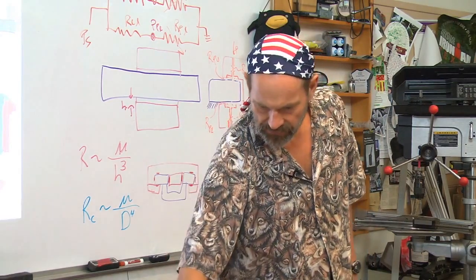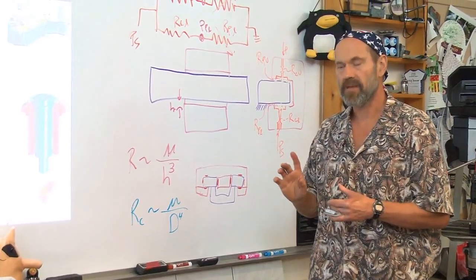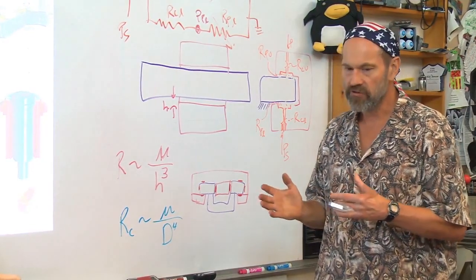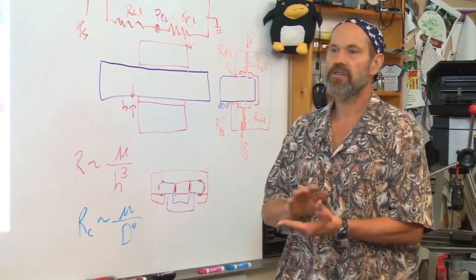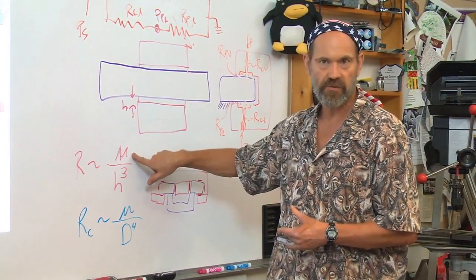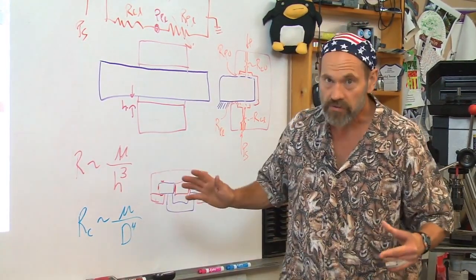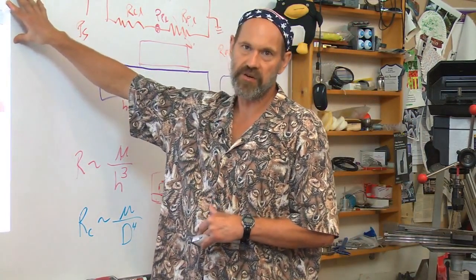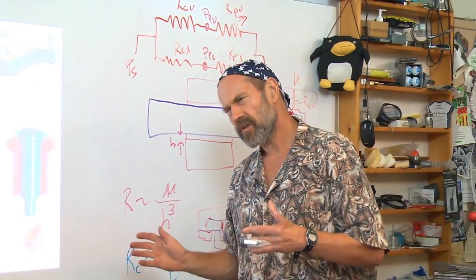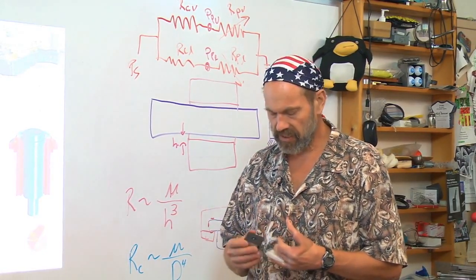Now, the other type of hydrostatic bearing, or aerostatic bearing, uses air instead of a liquid. For a liquid, you may use oil, and oil is very nice. The resistance that you need in your system is easy to achieve because of the high viscosity of oil. Oil can be an environmental difficulty sometimes, so you say, well, we use water, and we've designed and built a bunch of water machines, very high performance. The water self-cleans the surfaces, works very well. But you don't always want to have a lot of water blowing out. So what else could you use? Air.